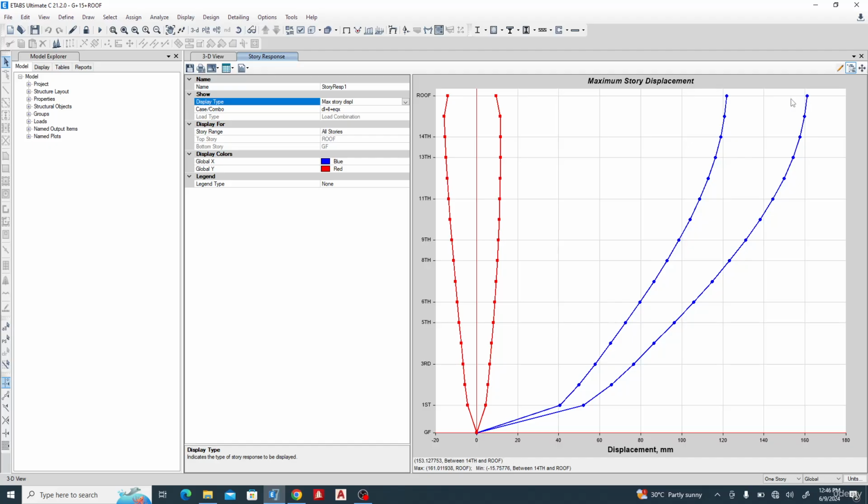So the only two things we can do here is, one, if we want to use first order analysis like this, we have to place a shear wall, a bracing element, which will take the sway, which will take the displacement rather, or we can decide to do second order, which is P delta, and will create a moment amplification factor. But that will be another video in future. But for this video, we'll be putting the shear wall. So let's create a shear wall and let's see the effects of it, how it will reduce it, in the next video.